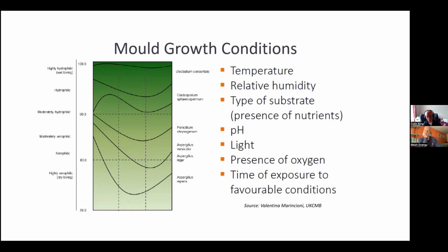So conversely, if you've got a building that was built before 1920, 1930, which was originally vapor open, it would be clay bricks or natural stone with a lime-based mortar. It would have had a lime-based internal finish, be it lath and plaster or even just lime plaster. But the coherence of that structure is that it allows moisture to move from outside to in and inside to out. If you then put in a vapor closed material on the internal face, you're actually disturbing that coherent strategy for that wall.